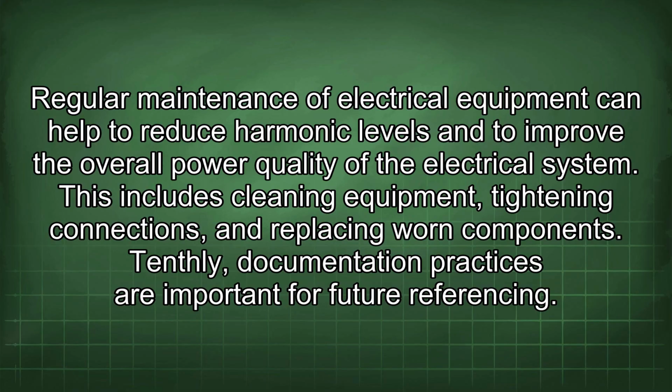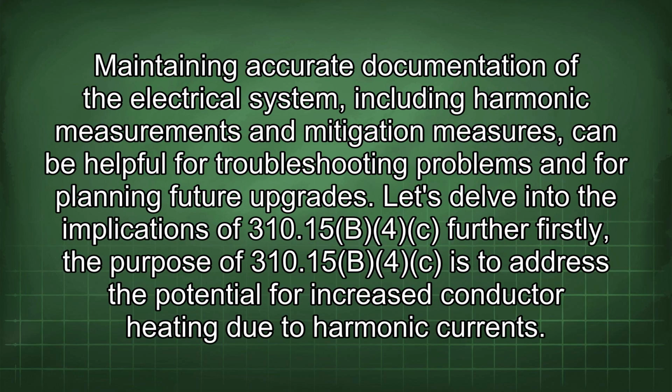Tenthly, documentation practices are important for future referencing. Maintaining accurate documentation of the electrical system, including harmonic measurements and mitigation measures, can be helpful for troubleshooting problems and for planning future upgrades. Let's delve into the implications of 310.15(B) further.